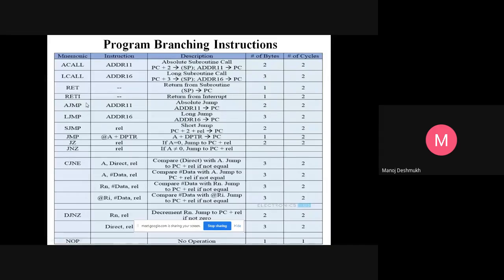And if the program counter is pointing towards the interrupt service routine, ISR, then after complete execution of the ISR, you have to mention the instruction RETI, return from interrupt, so that your program counter will shift back to the main program from which it was suspended, and continue from that instruction.